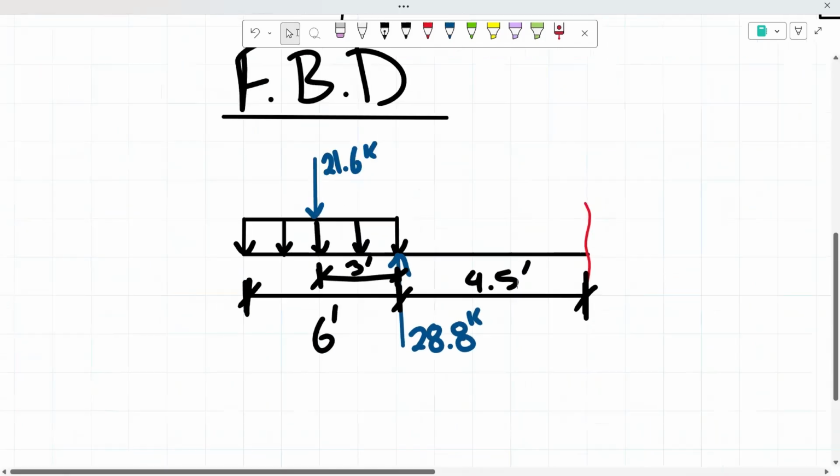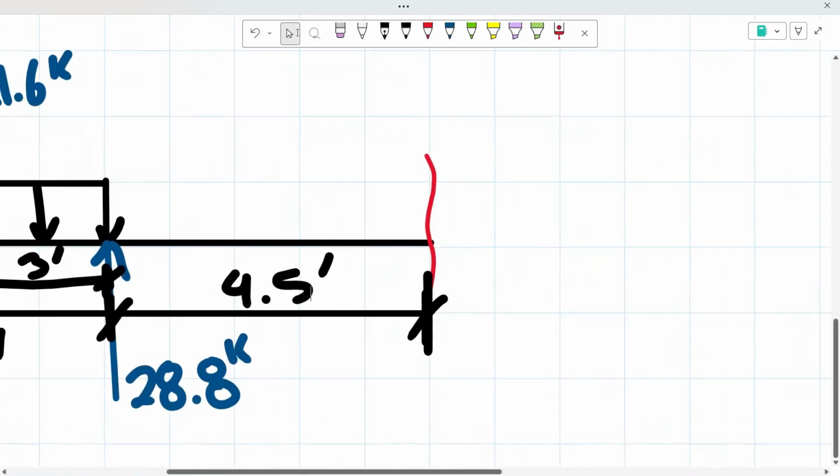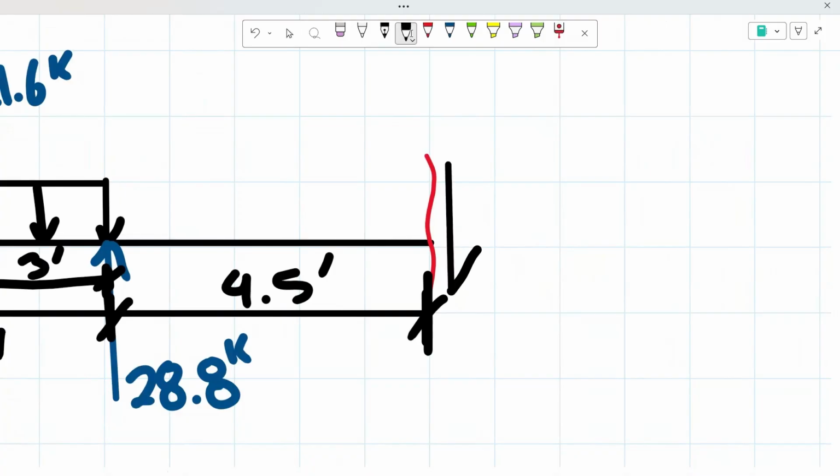So now that we have that, we can now continue to draw out our normal force, shear force, and moment. So remember, this is where our sign convention comes in. Since our cut is to the right side of the beam, that means that our shear force will be acting downwards. But we know this because of our sign convention. We're going to denote our shear force with the letter V. From there, we know that our normal force will be going away from the cut. So in this case, to the right. We're going to denote that with the letter P.